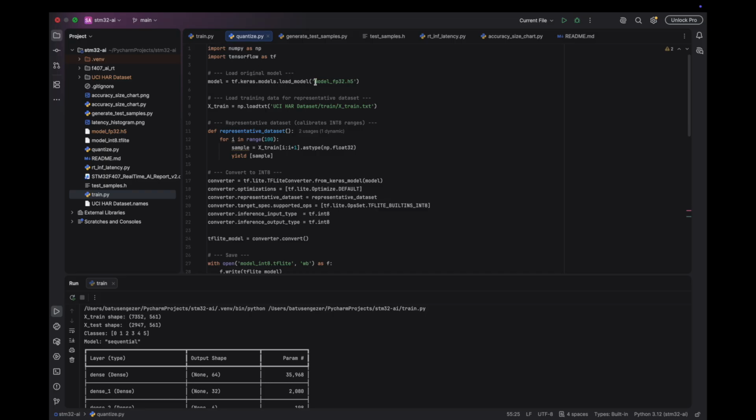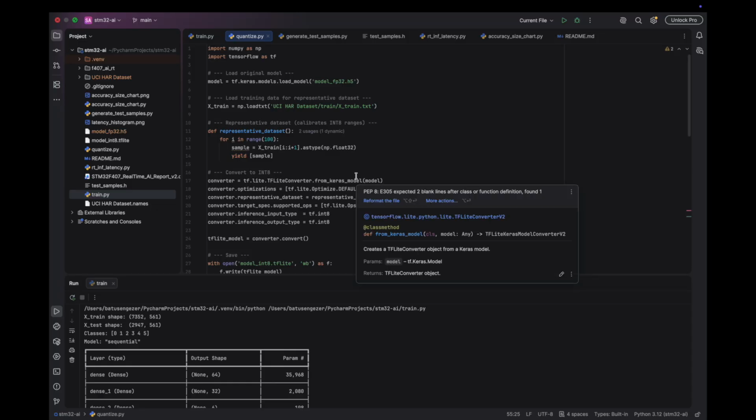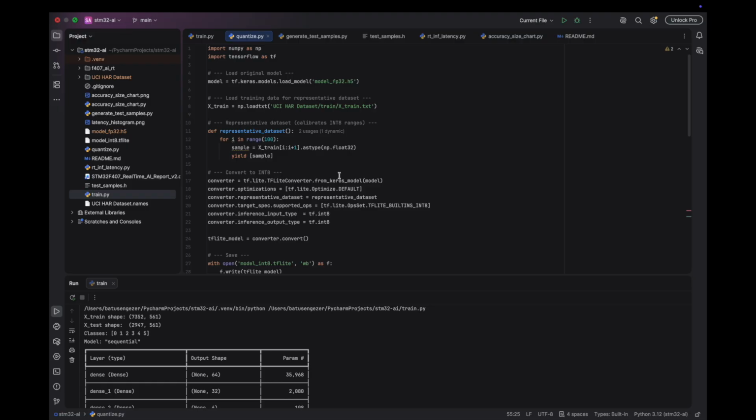This compression step is called quantization. What it does is convert every weight from a 32-bit float into an 8-bit integer. You lose a little precision in this step, but you gain enormously in size and speed, and on a chip with integer SIMD instructions, the hardware is exactly good at 8-bit math.